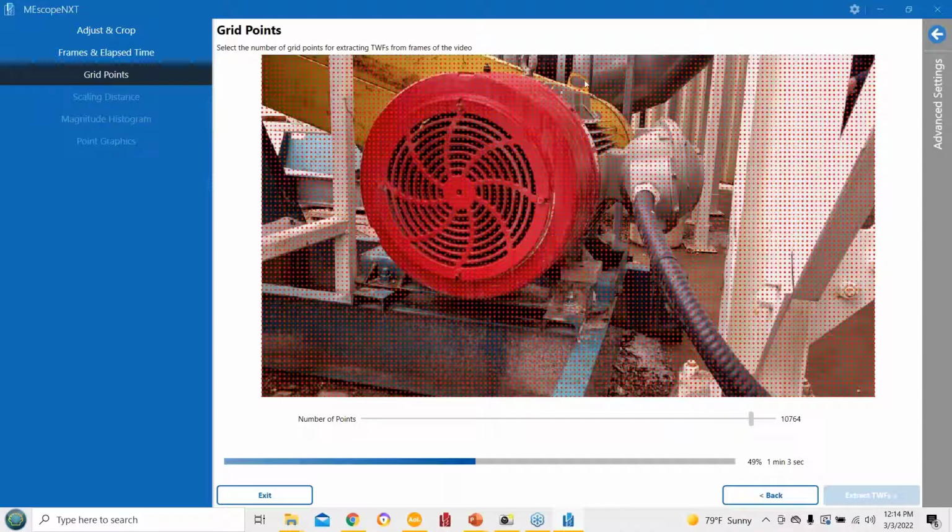So I want to turn all this off. I want to turn off anything in the background around the operating unit, and what it'll do is it'll calculate the background, and it'll take the average, and it'll subtract that average background motion from everything, okay? And then it will set all the points selected in the background to 0. So now what's really moving is just the parts that should be moving, and it should be at the correct amplitude, or much closer to the correct amplitudes. So I still have 30 seconds, and I talk fast, but maybe I ought to slow it down a little bit.